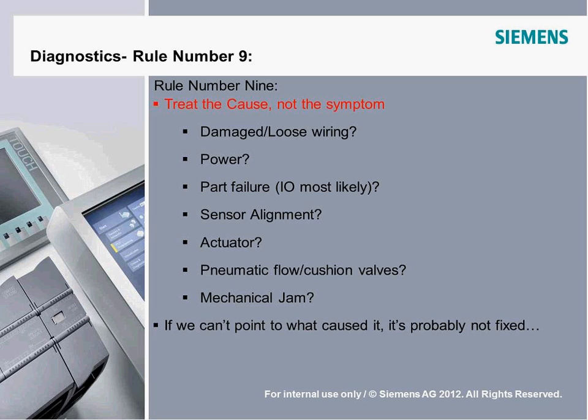Cushion valves are another. Cushion valves are so that when a cylinder gets to the end, it doesn't slam into the very end. It's just a little valve that gives it air compression and is supposed to bleed off and slow down the cylinder at the end. That can oftentimes cause a big problem with sensor alignment. If a cushion valve is stuck and not allowing full extension any longer, we may not be making our sensor alignment for that reason. If that's the case, moving the sensor is going to be a short-term Band-Aid fix, but it's that cushion valve that is the cause.